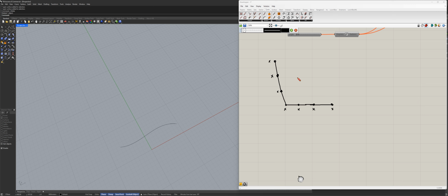It constructs them through a cross product, but I will not tell you the actual positions because it depends on the tool. Rail, sweep, loft, patch, whatever it is, they're different. Some use straight linear interpolation, some use it only on the edges like here and the inner ones are different. I will not specify. It's pretty heavy duty mathematics, and it's not connected to NURBS actually.